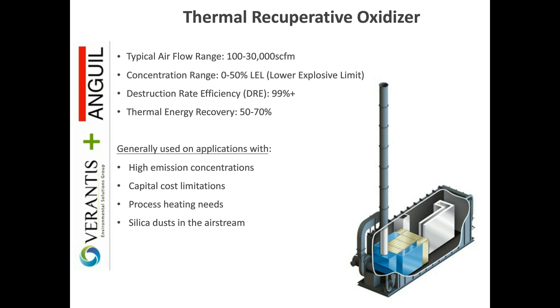So where we would see these applied are where there's a silica dust type of application, like a silicone coating line, where those silicone vapors, when oxidized, will actually create a solid silica dust. That can cause some problems within an RTO in terms of plugging up the ceramic media, and with catalyst as well, it'll plug the catalyst blocks. So that's where we would see these applied.